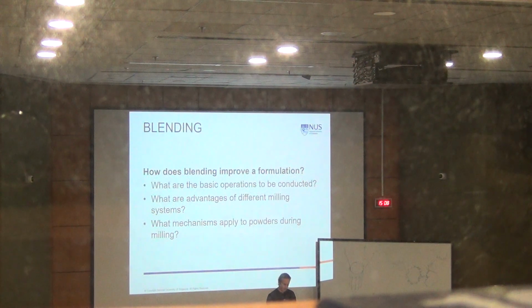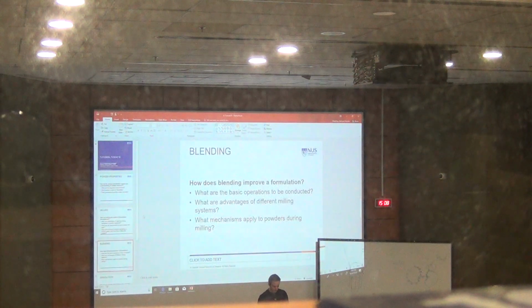This happens because of two things. First, magnesium stearate is just not a very stable material. It can break, but it's also quite sticky. And this means that over time you're generating agglomerates, and when you mix too long, the mixture gets less homogeneous. This can happen. And this is an effect that is usually not explained by common sense. This is why I also mention it.